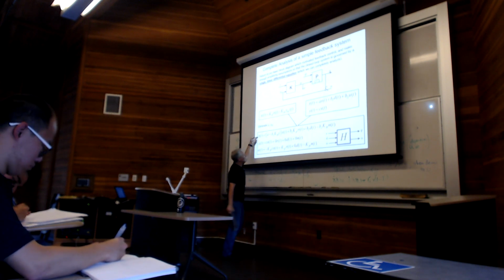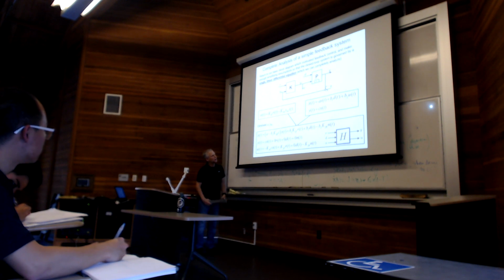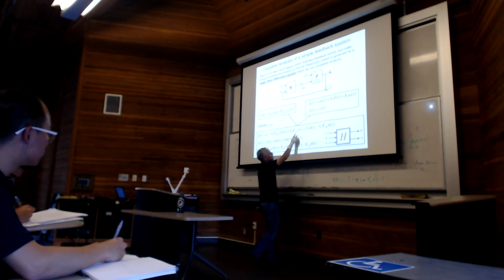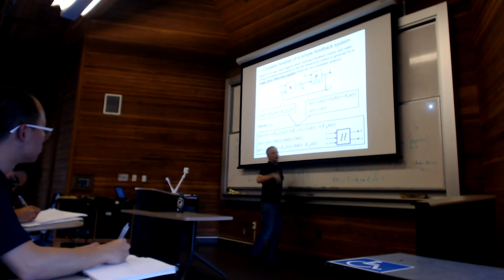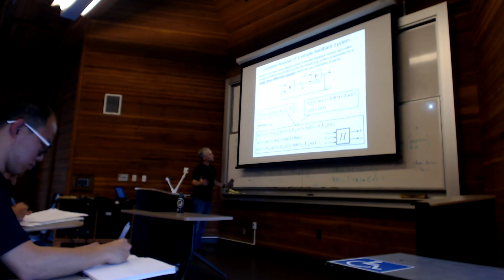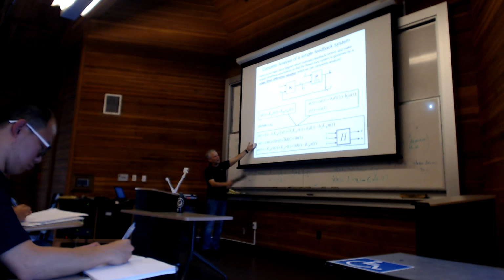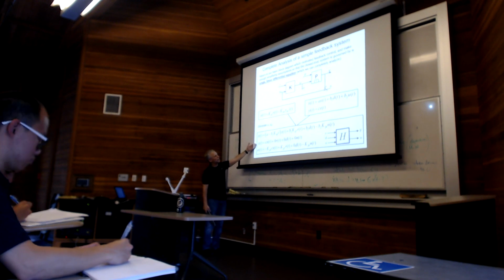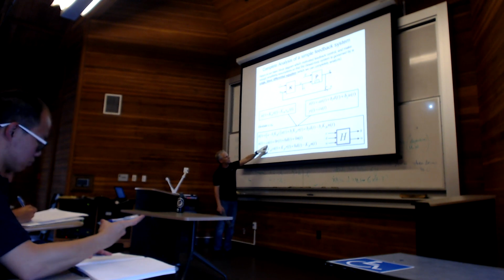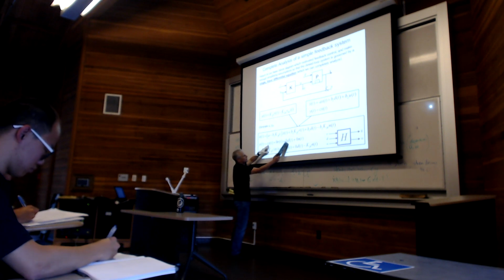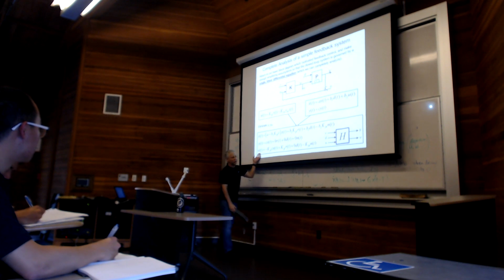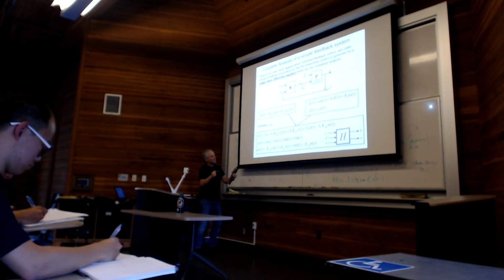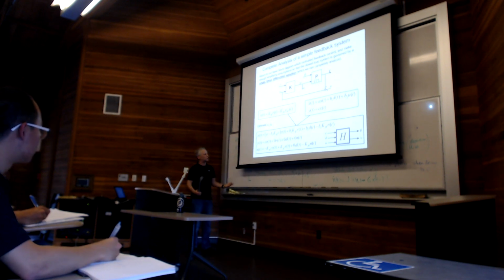So now I've got exactly how x behaves. It's driven by three things: r, d, and n, and there's x inside here. What are the two variables that I usually care about? I usually care about the output of the process, because that's the thing I was trying to regulate. That's just c times x, nothing times r, nothing times d, nothing times n. The other variable I'm often interested in is the one doing all the correcting, so I'd like to see how it's doing the corrections.